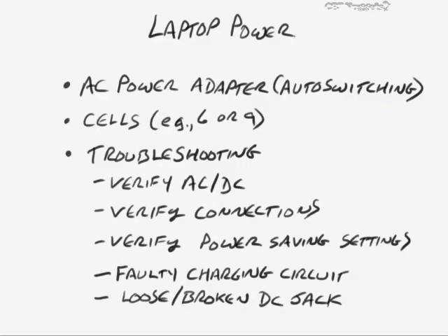Now, although I have a whole section on laptops alone, I do want to cover laptop power here since we're kind of on the subject. And I want to identify that you will have an AC power adapter, of course, for your laptop. These are usually auto switching, so you don't have to worry about those. In fact, if you look on them, it'll usually say somewhere around 100, 110 volts to 240 volts input. And then it'll say whatever the output is, which is usually somewhere between 18 and 19 volts, somewhere in that range. So those are going to switch themselves, and they're a little bit inconvenient.